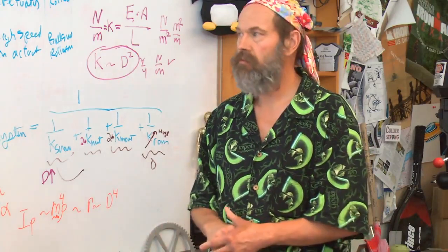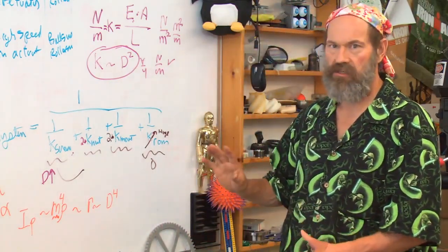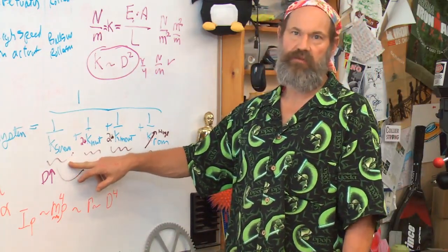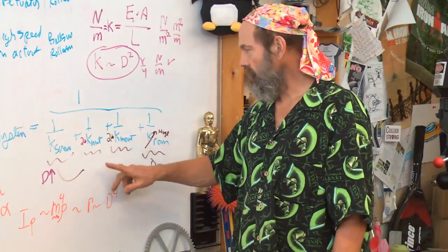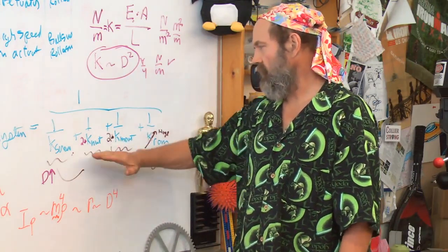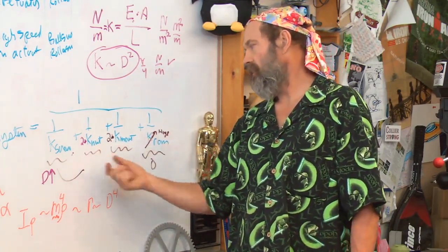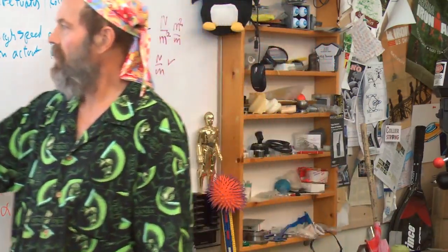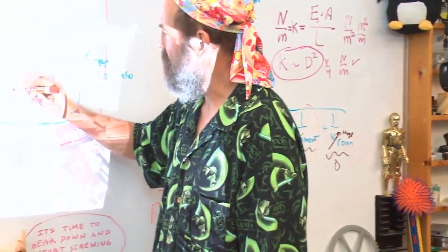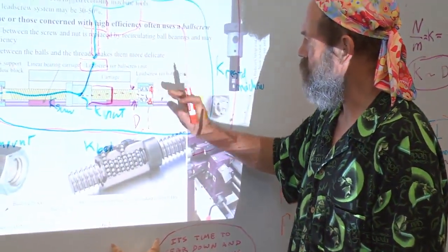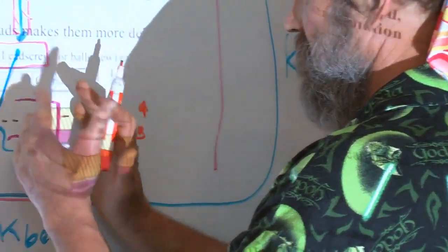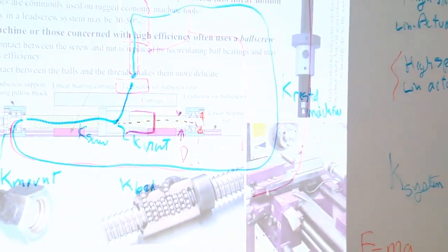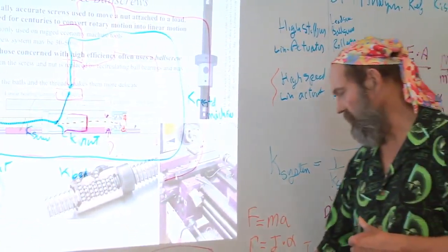Ouch. It's not a wise design decision for a high-speed machine where you want to get the stiffness up just to increase the diameter of the screw shaft. You're better off doing things like a longer nut or figuring out how I'm going to be able to make this bearing here anchored to the screw and accommodate the fact when it gets hot, the screw wants to grow and then buckle. So let's look at that design problem. How would you handle that?